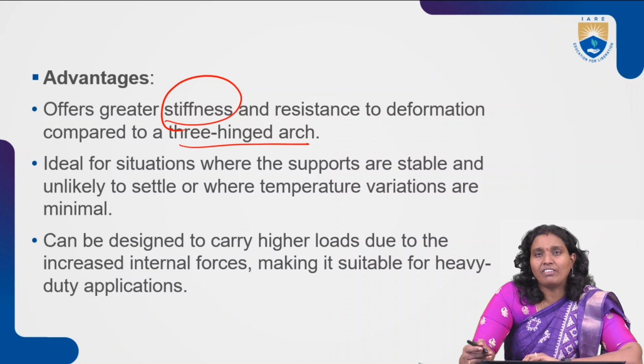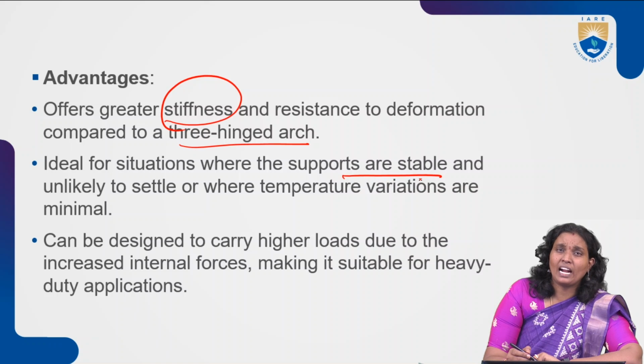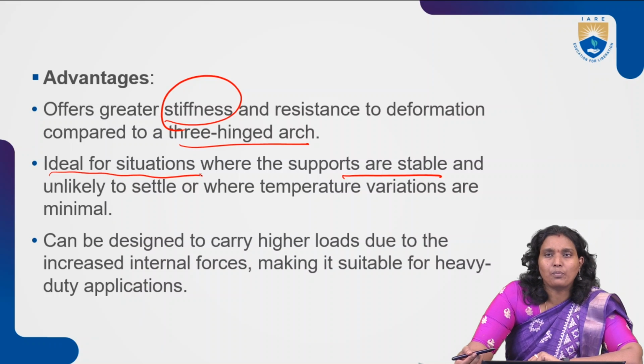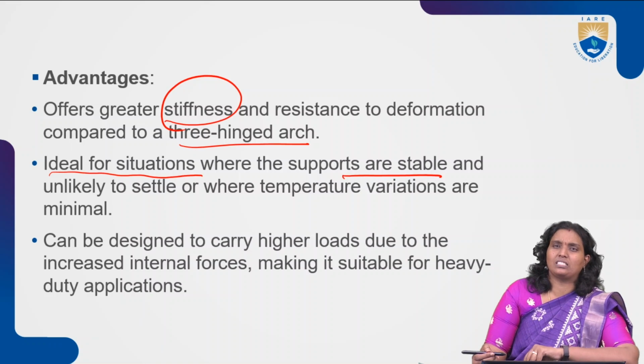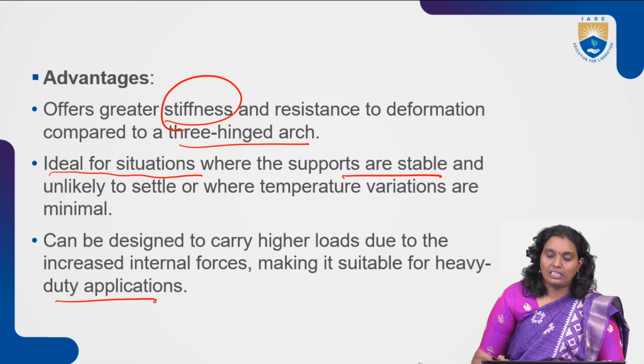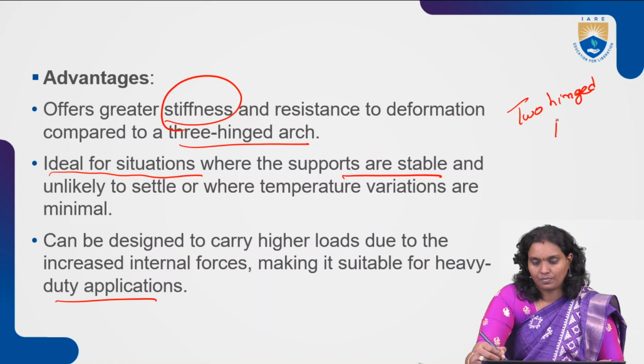It is ideal for situations where the supports are stable and unlikely to settle, or where temperature variations are minimal. They can be designed to carry higher loads due to the increased internal forces, making them suitable for heavy duty applications. These are the advantages which we are going to understand in our two-hinged arches.